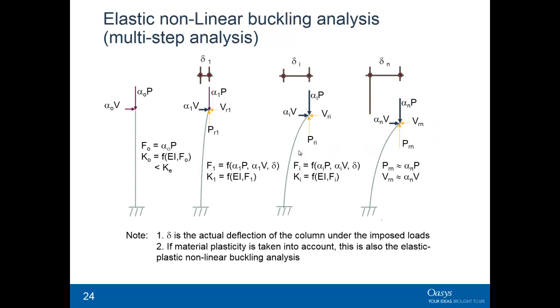With the non-linear member buckling, though, it's slightly different. Here, GSA will increment the loads and measure the deflection at each point up to final failure point, and thus the deflection is correct. But you only get the one set of results.